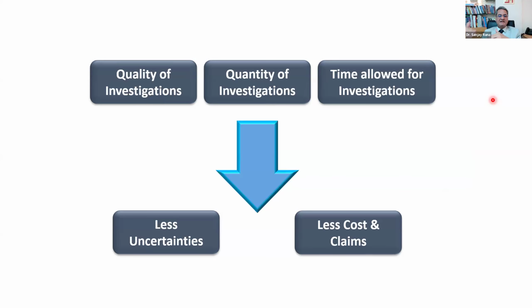Look at this diagram here. There is a void here, there's a limestone pinnacle, and there are a few anthropological features. If you're only depending on drilling, the chances that you will detect any of these isolated features is 1 in 1,000 or 1 in a million, depending on the spacing between your drill holes and the size of these objects. Whereas if you do a good geophysical campaign, you will detect and map all these anomalies irrespective of their size. All right. That is why it's so important to have continuous information.